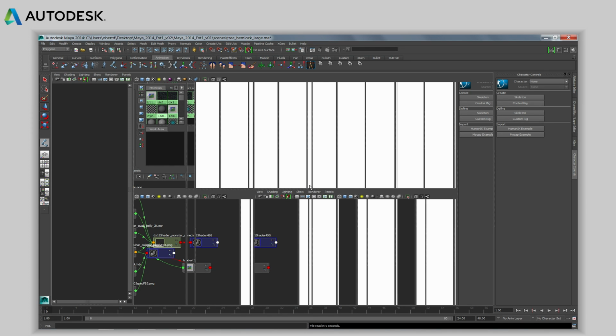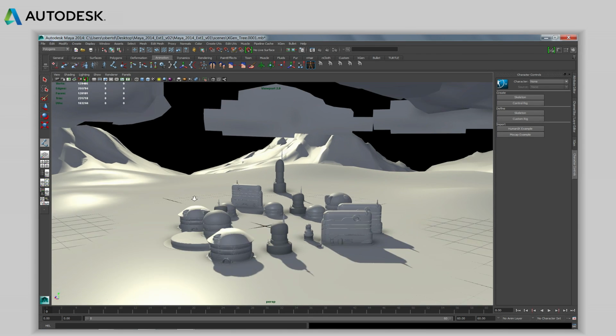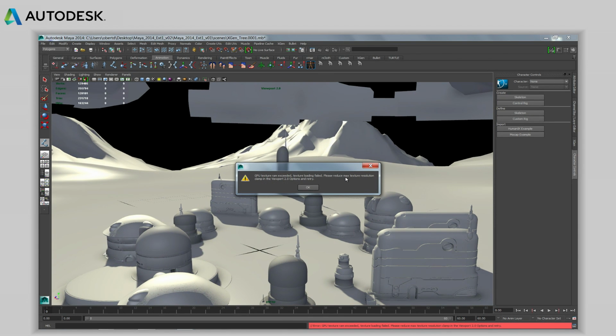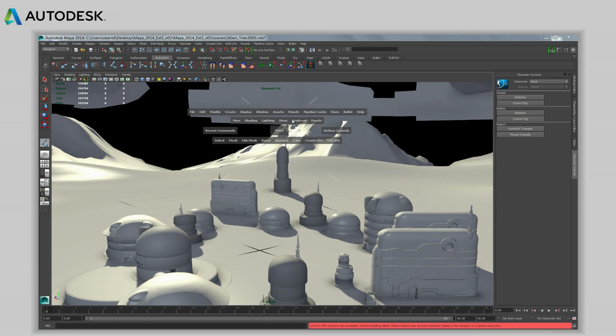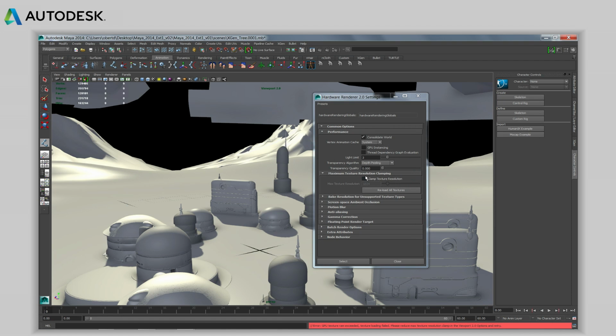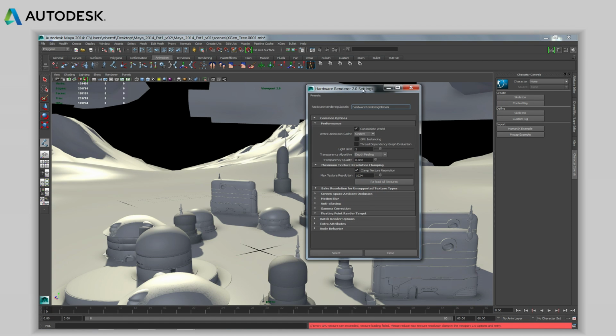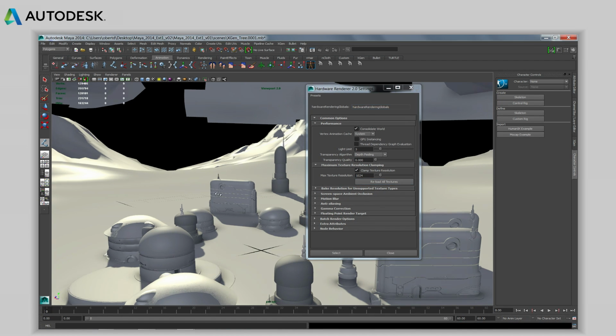And that archive that we saved out earlier. Looks like I'm running out of texture memory. There's the downside of laptops. So let me show you how to get around that. If you go to your viewport and clamp your texture memory, it will reload all those textures.